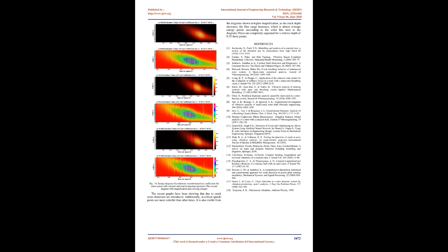Fig. 9. Fourier transform diagram when the vertical axis is on a logarithmic scale for the operation of a transient rotor mode with a healthy shaft and cracked shaft with various depths, the second diagram with magnification. Compared with Fourier diagrams that have been plotted for steady-state operation above, Fourier graphs in the case of transient state do not show any profitable details concerned with crack effects.